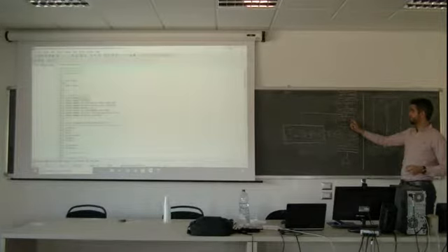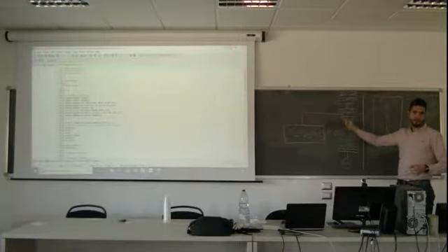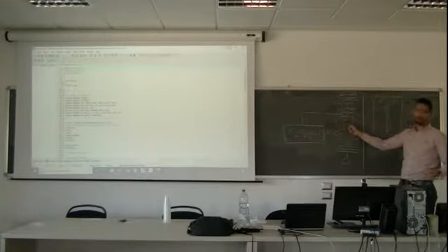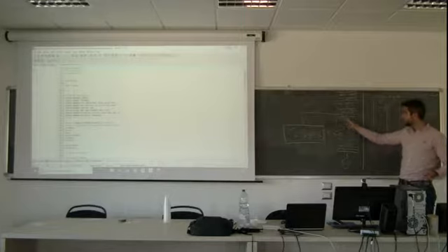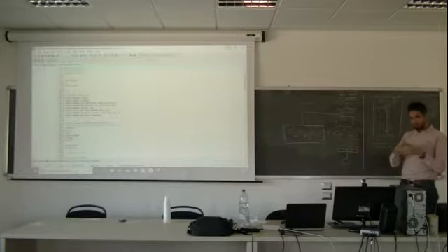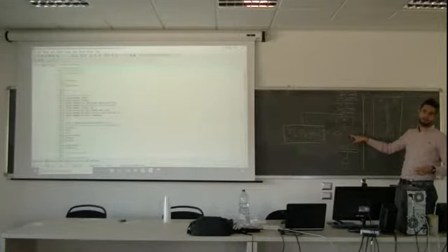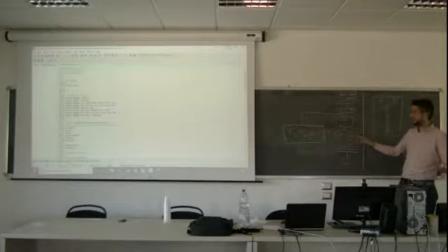Then you go to the equations. For i equal to 0, you have one equation. For i equal to 1, you have another equation. For i equal to n, you have another equation. So you compute the temperatures 0, 1, and n. Then you compare: the map of temperatures that I got from the solution is different from what I assumed. The asterisk stands for the assumed map.